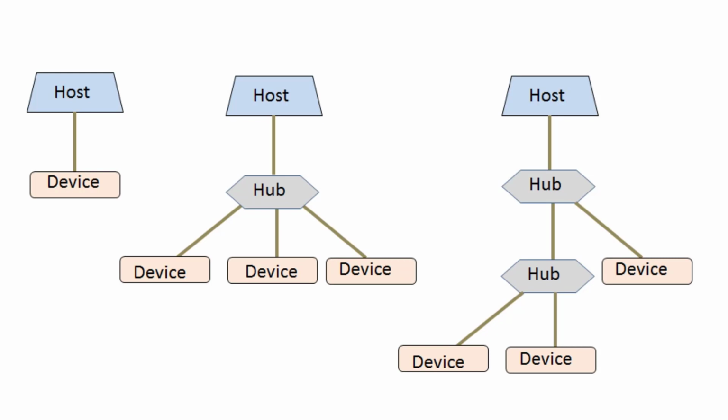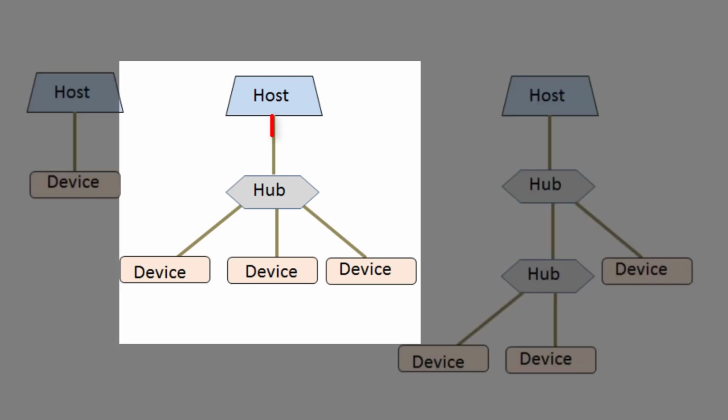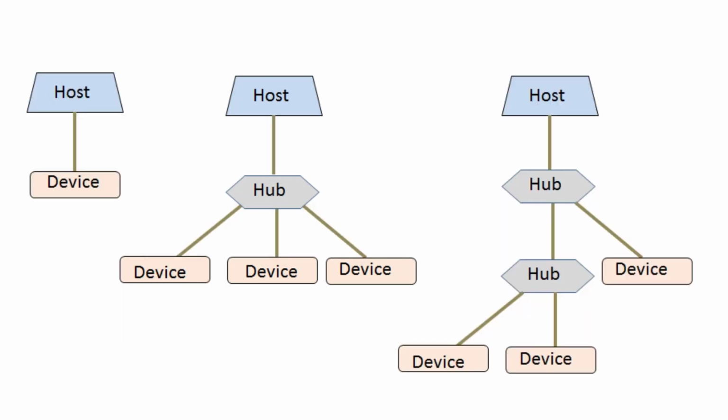There is some benefit with this tiered star topology. Firstly, the power to each device can be monitored or even suspended if an overcurrent condition occurs without disturbing other devices on the network. We can also have low speed and high speed USB devices on the same network with no problem.